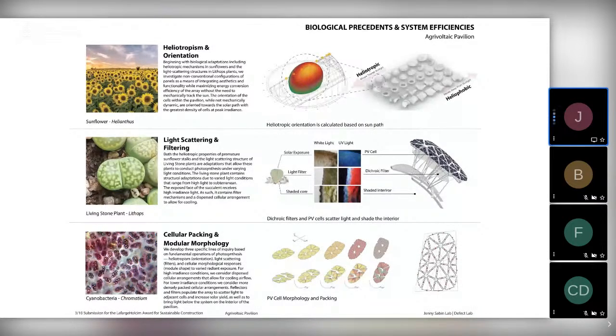Our proposed collaborative approach follows solar path data and omits the typical 50% additional structural metal and 30% copper cable in traditional BIPVs per module, which can significantly decrease the carbon intensity by 15% for the case of an installation in the Southwest. So by working with non-standard componentry and leveraging 3D printing, we're able to design more directly with the dynamics of light conditions throughout a typical day and over seasons and annually.